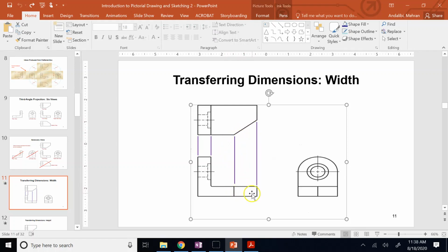So this is a plane that if you look at it from the front, it would look like a plane, but if you look at it from the top, it would look like what? An inclined edge. So this is a plane that is basically at an angle with respect to the front plane, okay? So this projection that you see is actually a little bit smaller than reality. So it tells you how the plane is positioned or oriented in space.